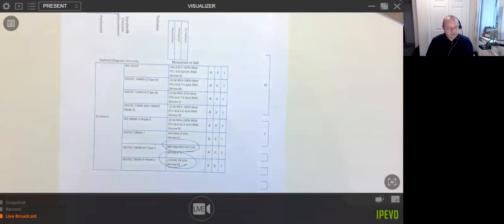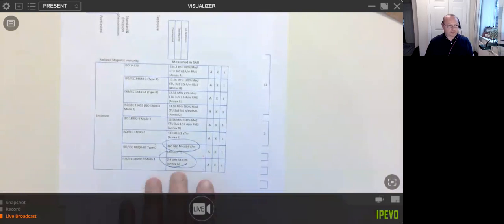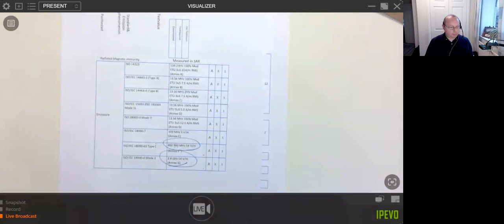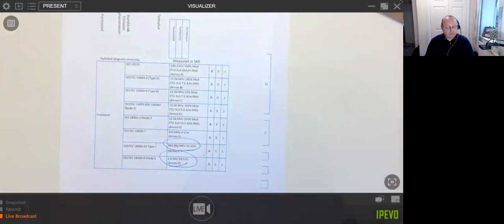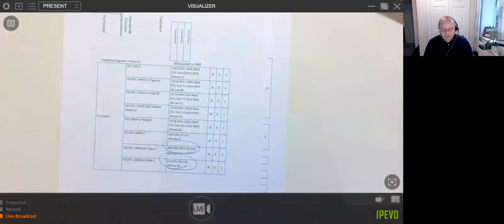Something like 1 volt per meter is nothing. Nothing will happen at 1 volt per meter. All electrical equipment, I'm looking around my desk here, I've got my mobile phone, my oscilloscope, my PC screen, that's all 3 volts per meter. So what you're looking for, and it's up to you, the designer, and the company to decide, is what is considered acceptable for that level of immunity.